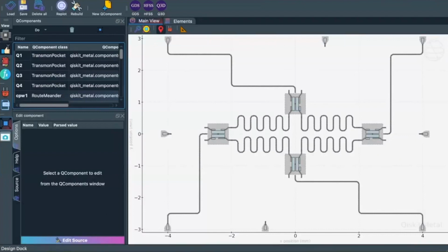In terms of the Hamiltonians that you put out, I think that's work we're currently building up. I'm hoping we can leverage some things like SC qubits, if you're familiar with that, that have that already defined, so we'll build out that interface from there. But right now, the thing you can immediately do is just change the inductance LJ and use that as your flux knob, essentially. I see. Thank you. I'll try it out. Cool. Try it out and maybe Slack us if it's not what you meant.